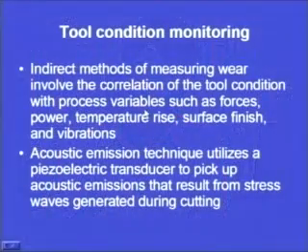So, if the tool is going to encounter an excessive wear rate, then it is going to have an influence on any of these process variables. Suppose we take an example where a cutting tool has been abraded or has undergone a substantial amount of wear. Then, if we are recording the forces, there will be a sudden increase in the magnitude of the forces that we are recording using a dynamometer.